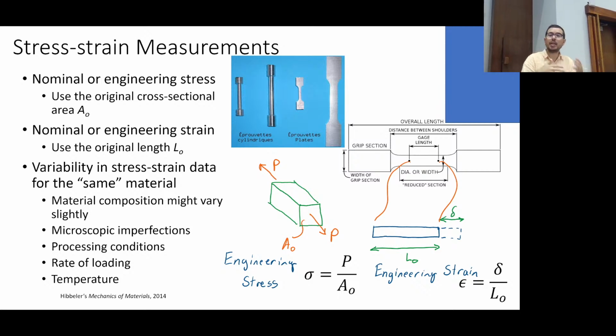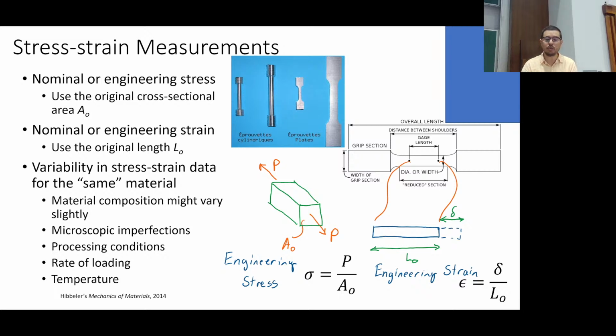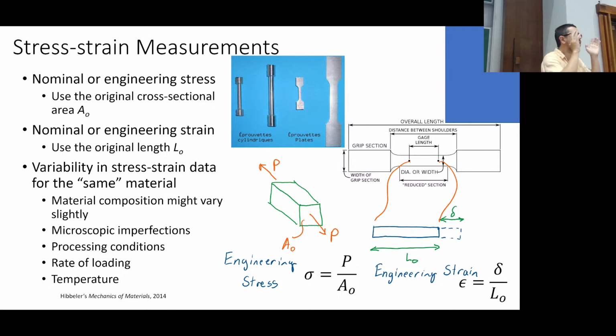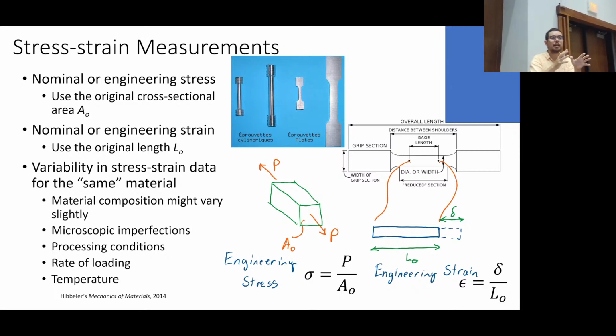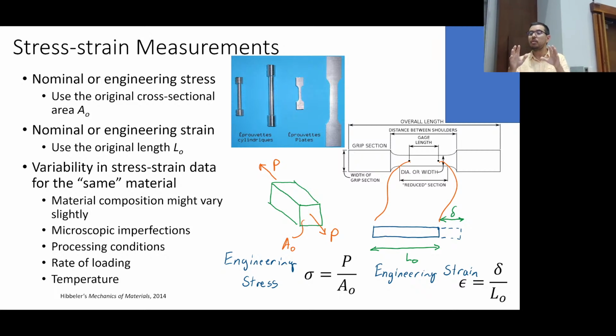Safety factors have come down as our ability to estimate conditions and run simulations has improved. But for your furniture and various things, you can have pretty significant safety factors. So you should only apply 33 newtons if I do a safety factor of 3, even though I know in my material testing it's going to break at 100 newtons. We add some extra safety in there.